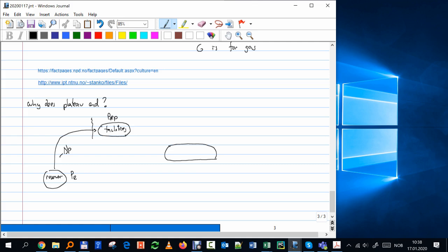But here on the facilities, this pressure is usually kept fixed, except in very few cases. And the way it is kept fixed, I guess you have seen that before. The main separator is called the high pressure separator. It has a few control measures that are making sure that this pressure is constant. If we make it very generic, we have gas, in a very simplistic way, and oil.